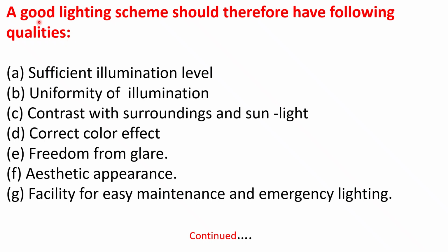Friends, a good lighting scheme should therefore have following qualities: sufficient illumination level, uniformity of illumination, contrast with the surrounding and sunlight, correct color effect, that is CRI, freedom from glare, aesthetic appearance, facility for easy maintenance and emergency lighting.